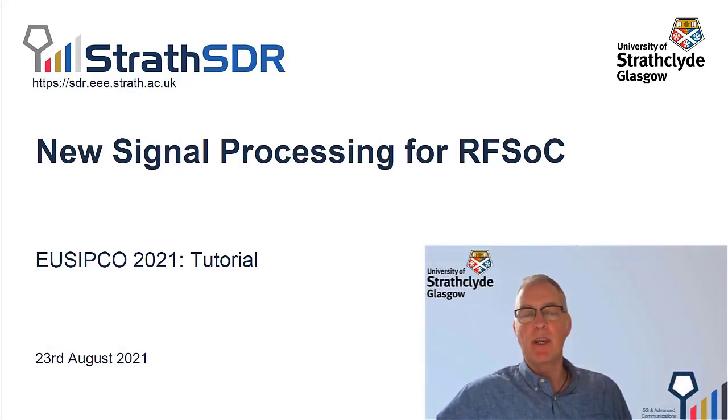So in this section of the presentations, we're going to talk a little bit more about the digital signal processing that leads to the software-defined radio at the physical layer, all supported by the RFSoC. So we'll consider first just the history of QAM architectures, looking back to how baseband, IF, and now RF sampling has come about. We'll then discuss sampling and first-order zones and second-order Nyquist zones, and then look at the ADCs and the DACs, and how we do some very interesting new bits of signal processing to make sure that we can work in both the first and the second order Nyquist zones.